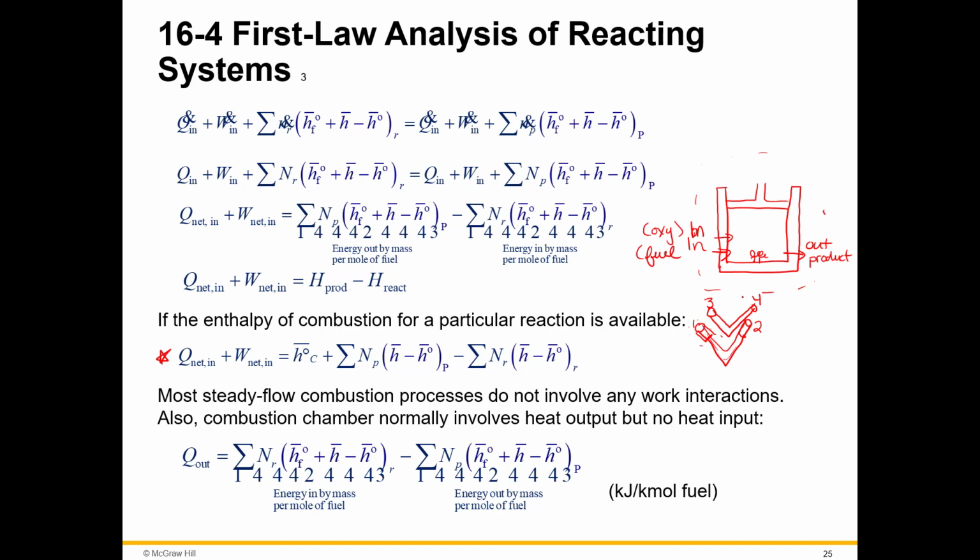And so if you have a V8, you're going to have 4 of these V's, and you're going to have 8 cylinders, okay? So here we're just going to do a 4-cylinder. In each one of these, you have an in and an out. And these are going to be cycling through the shaft. It's going to be pushing the rod up and down and up and down. And so what happens is you have fuel and air come in. When the piston is pulling out, when it's expanding, it's going to be pulling in oxygen and fuel in the right ratio.